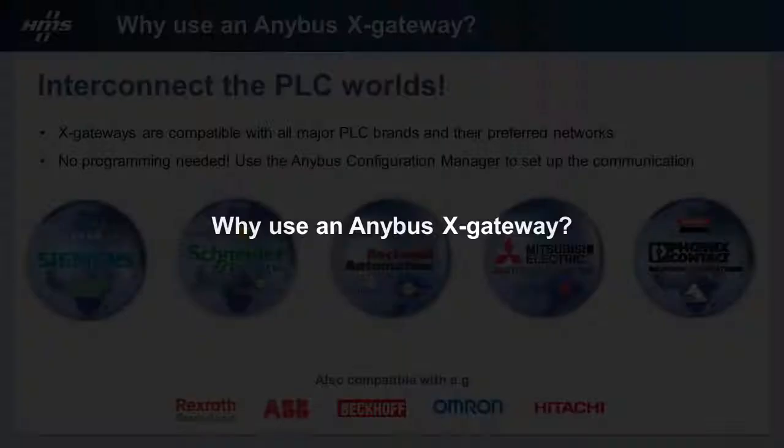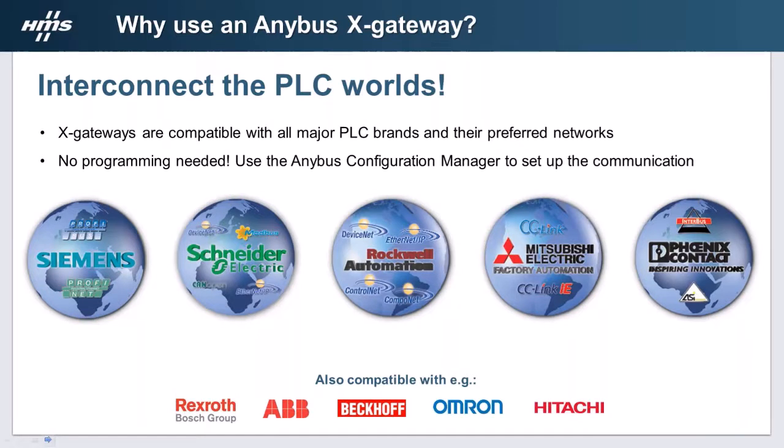Okay, why bother? Let's have a look. As I mentioned, and Bill mentioned as well, there is a wide range of protocols around, because in most manufacturers' dream worlds, you would buy everything from them, the PLCs, the drives, everything. So it's in their interest to have their dedicated protocol, and some would argue they also think they know best too. But it is something that hasn't harmonized. There have been several attempts over the years to come up with a common protocol, and every single time it's come to nothing, because there's nothing commercially in it for these manufacturers to do that. So that's where the X-gateway comes in. It means that there's no programming involved. You've got a solution to get differing networks to talk to each other.